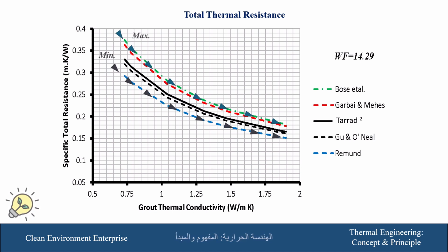We have the same trend for these curves, and as the thermal conductivity of the grout material increases, we will get a lower total thermal resistance, which is related directly to the depth of the heat exchanger required for a specific heat duty as well.